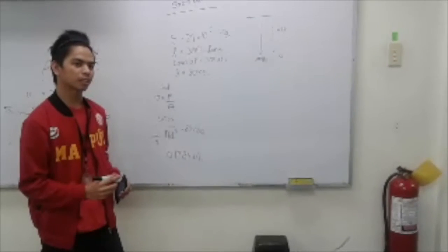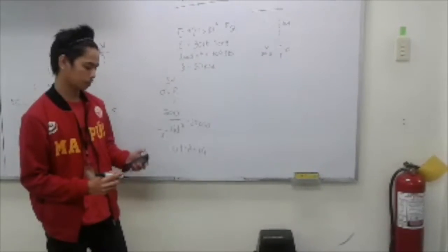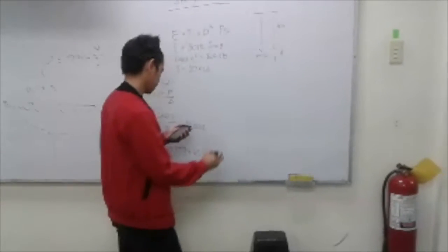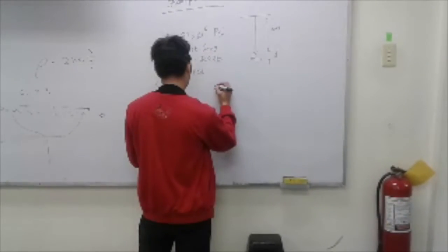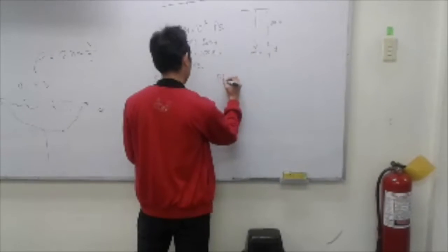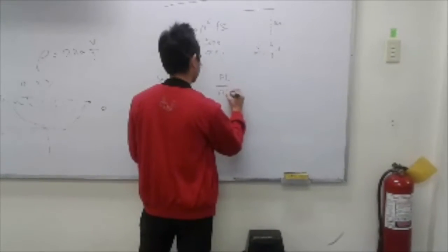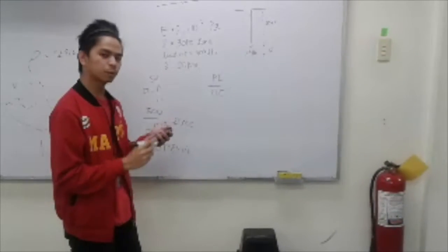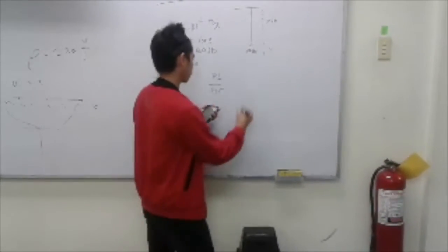We can still check if it will hold true, because we have another formula that we can apply, PL over AE, which is based on the maximum allowable deformation.